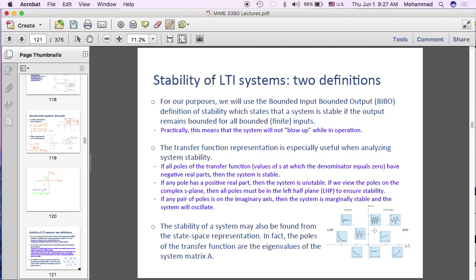And we never had this case, but if only one of the poles is to the right of the imaginary axis, you're dealing with an unstable system. Now, what does an unstable system mean? Unstable system means you give it a limited input, but the output is very large. It could lead to damage to the rest of the system or self-destructing the system. So it's definitely an unwanted behavior. So stability, my point is, can also be determined by location of poles. Even if one of the poles is to the right of the imaginary axis, you have an unstable system. And this is definitely unwanted. The response would blow up. So that's what you want to avoid, but you also want to tell if a system is unstable simply by looking at the location.